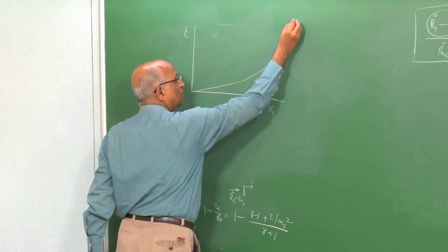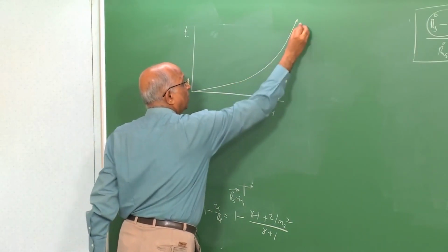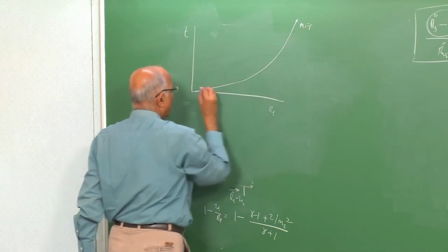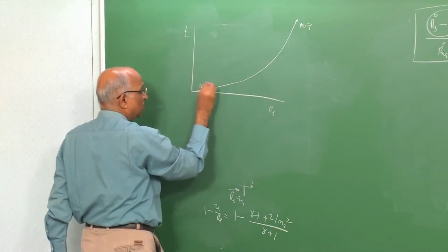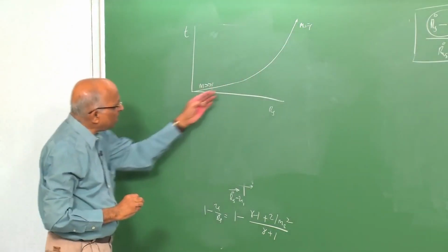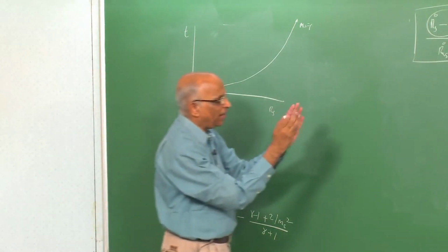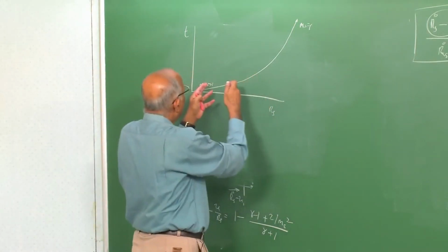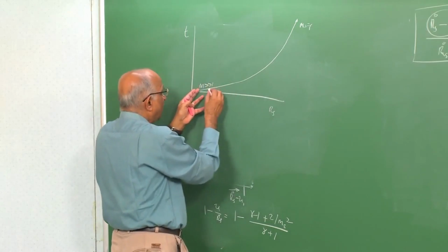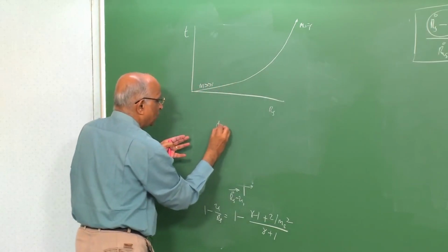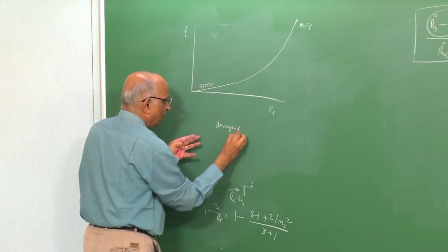Ultimately, it becomes an acoustic wave wherein the Mach number is equal to 1. It starts travelling with a Mach number which is very much greater. Now, it is a variable Mach number, and how do I use the results I have derived so far into the case wherein I have something like a decaying shock wave which is a blast wave.